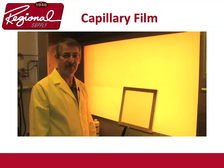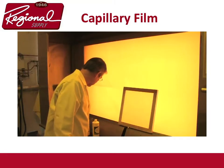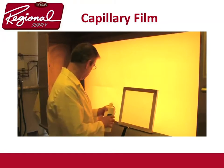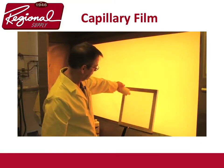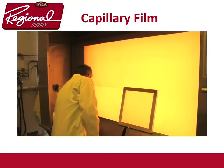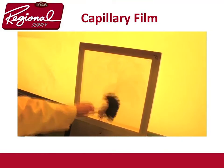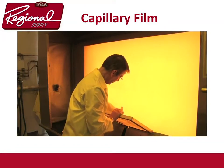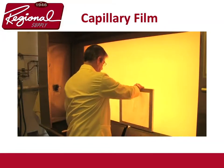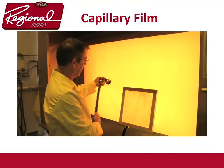All right, now the first step we have to do is we have to degrease this screen, because as clean as it looks, it is very dirty. So what I'm going to do is I'm going to grab my Chromaline and a hose. Wet the screen. Squirt on a little bit of Chromaline, not very much. Use a brush just for degreasing, and work this into a lather. Then I have to do the other side. There, I have now removed almost all the oils and whatever's on the screen, and I rinse it off.